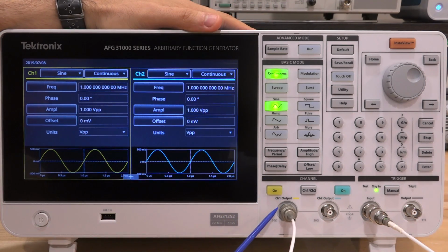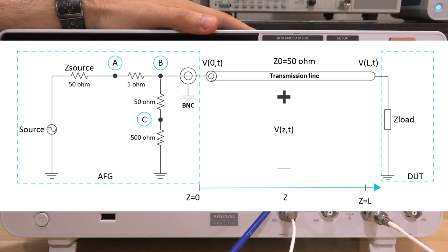So what they've done is that at the input there is a unidirectional resistive divider. It's basically a coupler made of 350 ohm resistors. And that coupler over there allows you to measure at 3 different points the signal present here. And that's some of the circuitry associated with that I discussed and showed you during the teardown.